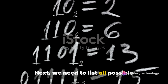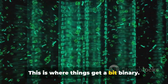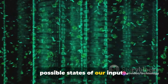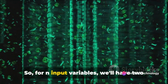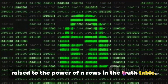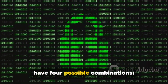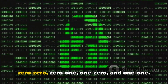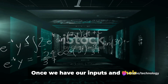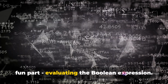Next, we need to list all possible combinations of these inputs. This is where things get a bit binary. We use zeros and ones to represent the possible states of our inputs. So for n input variables, we'll have 2 raised to the power of n rows in the truth table. For example, if we have 2 inputs, we'll have 4 possible combinations: 0,0; 0,1; 1,0; and 1,1.